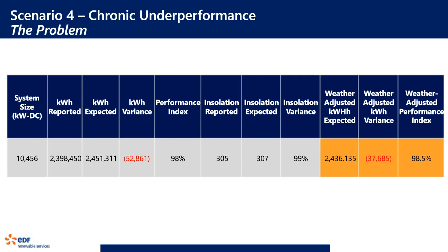So, from here, the next step is to start looking at, we're not seeing a mechanical issue out there that readily jumped out. We're not seeing typical problems. And, ultimately, then we start doing things like individual IV curve tracing of modules. Took a batch of the modules and sent them off to Fraunhofer for testing, thinking maybe we're looking at an advanced degradation problem, or something else. And at the end, we are several months into this and still really can't fully explain what's happening out at the plant.